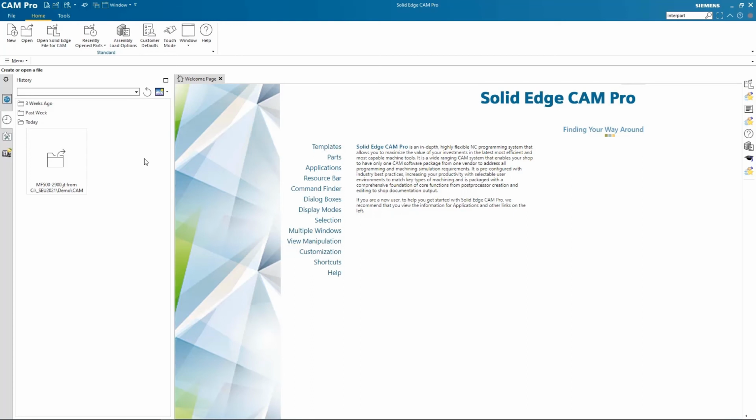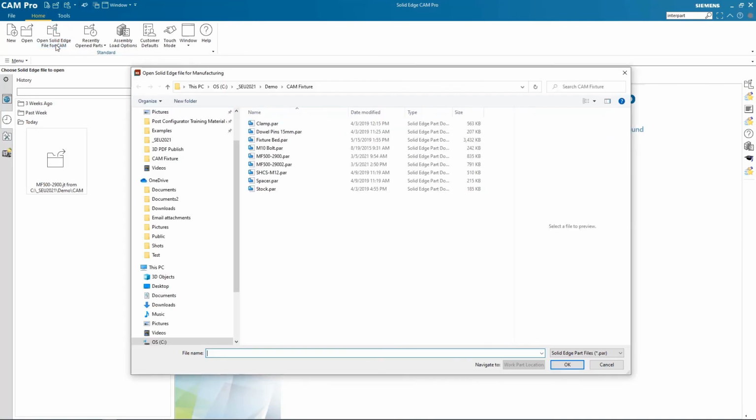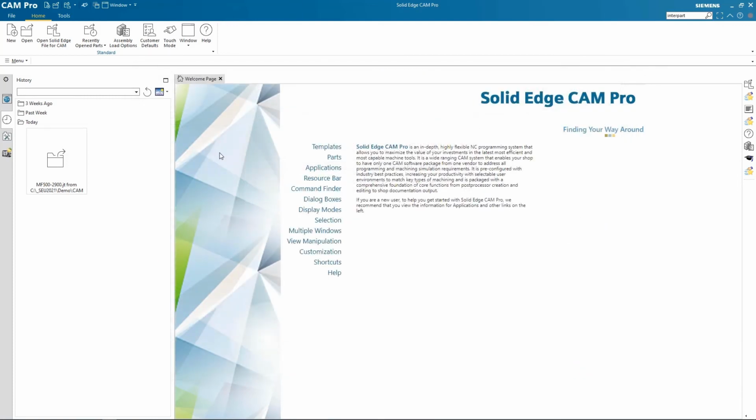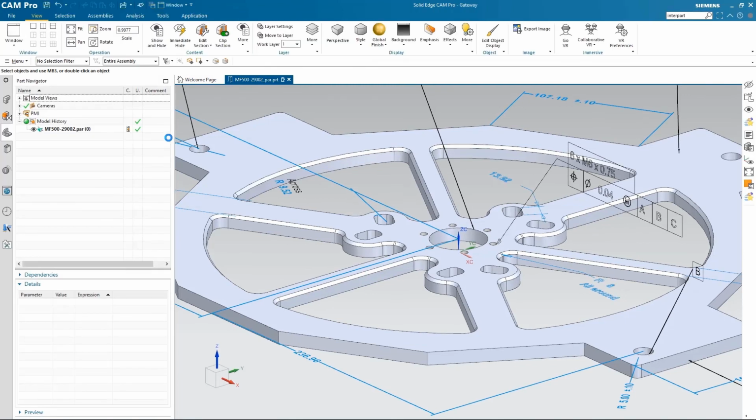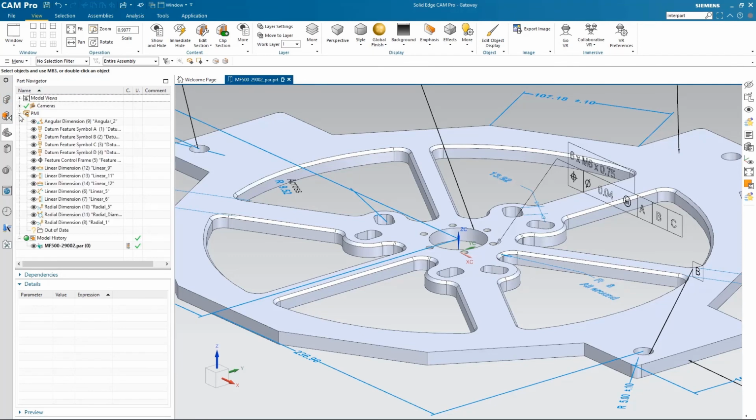You can transfer PMI data from Solid Edge models. It will happen through a PLM-XML adapter if you just simply open a Solid Edge file directly. And there are some settings that will impact that as well. So you can see they all come in and they'll be collected in the PMI collector.